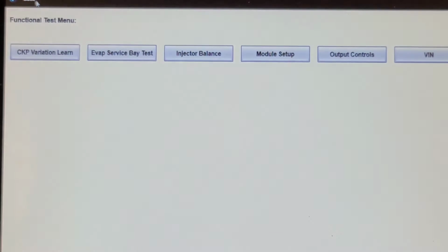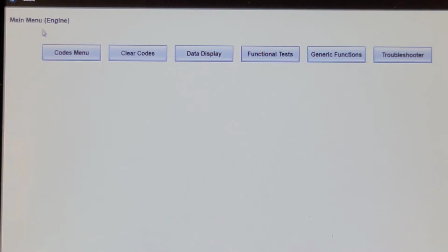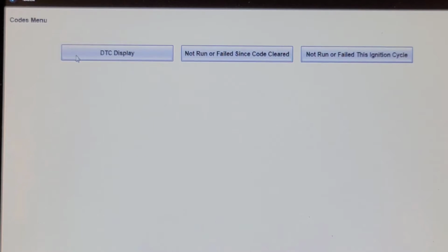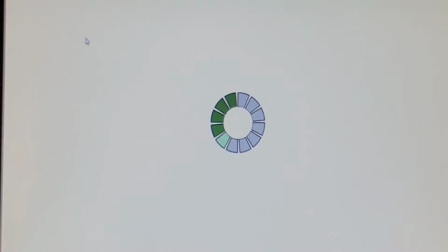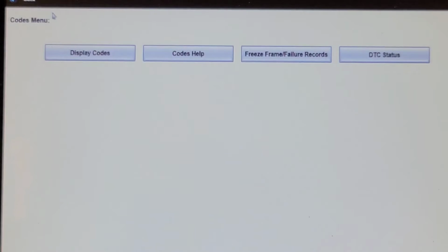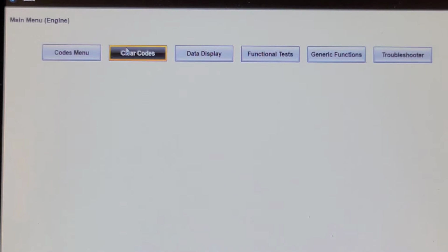So before we jump to conclusions and start checking continuity of the wiring harness, with that test light in there, it should simulate the continuity through the control coil, and there shouldn't be any codes. So let's clear this code, because I cleared it before, and it came back basically immediately.